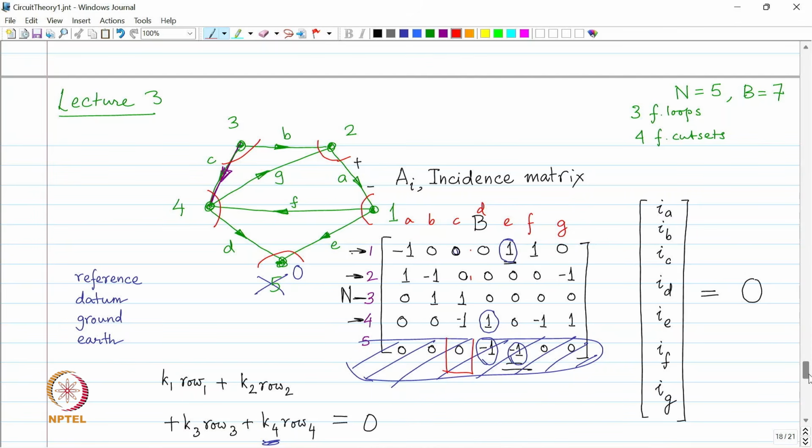In circuit number 1, I can have resistors, diodes, voltage sources, capacitors. In circuit number 2, I could have inductors, transistors, MOSFETs, something else, okay, nothing stopping me. But what do I see? I measure the voltages on circuit number 1, I measure the currents on circuit number 2 and do the dot product. That dot product is going to be equal to 0. Why?